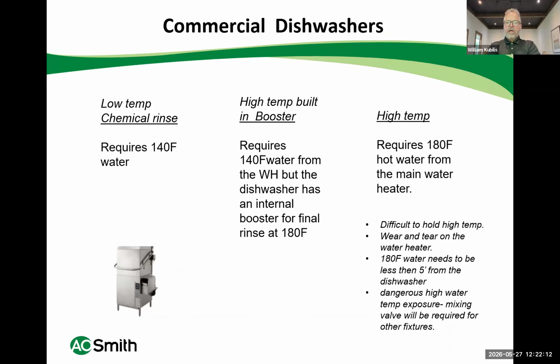High temp dishwashers with built-in boosters also only require 140-degree water, whereas the dishwasher has an internal booster to boost the water up to the final rinse of 180 degrees. Then I don't see these too often, but I still have run across some high temp dishwashers that require 180-degree water from the water heater.